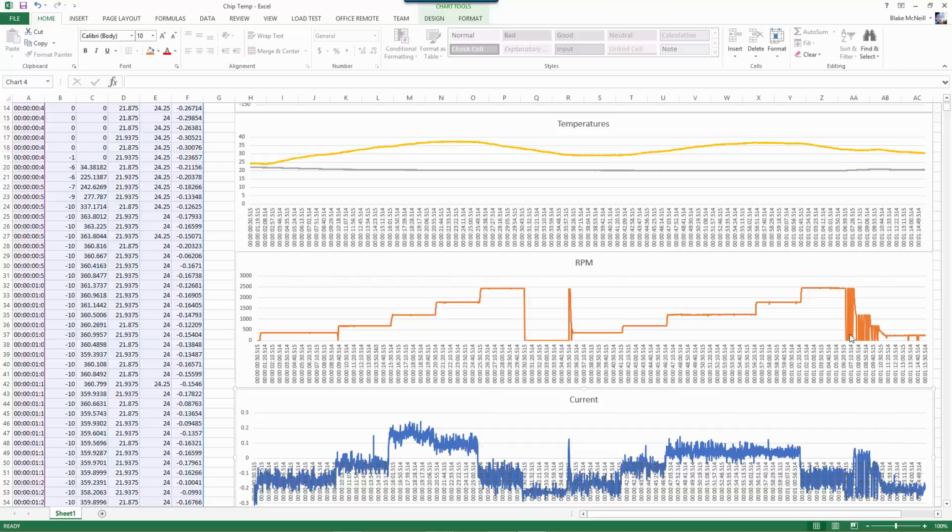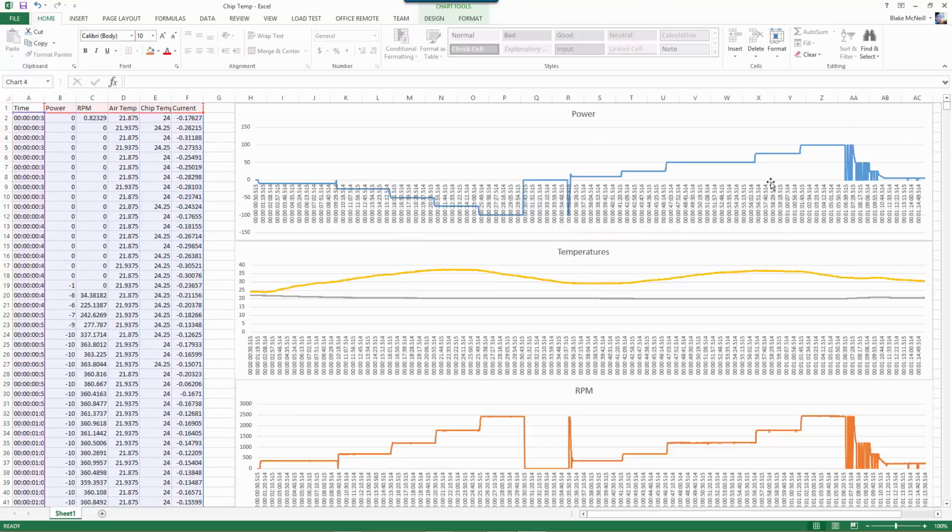Unlike using a rheostat to control power to a motor, where we divert some of the power off and run it through a resistor, which converts it to heat, pulse width modulation is actually very effective at utilizing power for controlling DC motors. And so I think we'll include that experiment as a successful proof.